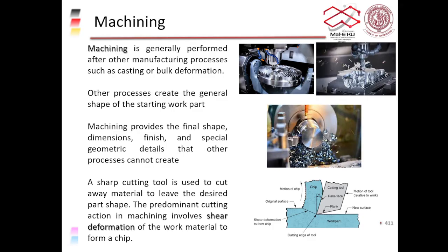So a material with good machinability is a material that can form small chips and move away from the surface easier. Like in this picture here, when you have chips flying away, instead of this picture here, when you have strips of metals clinging on to the workpiece and clinging on to the cutting tool, right?